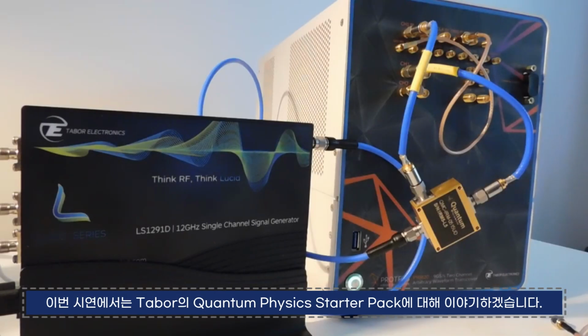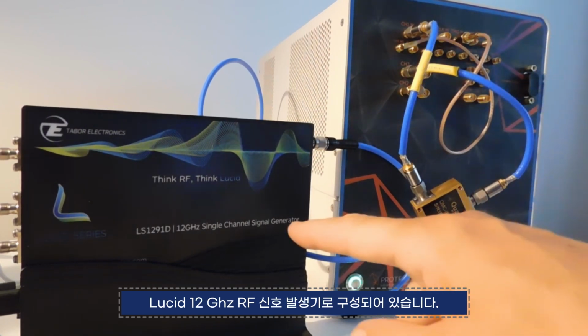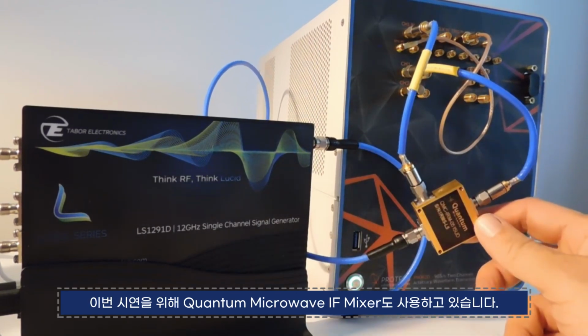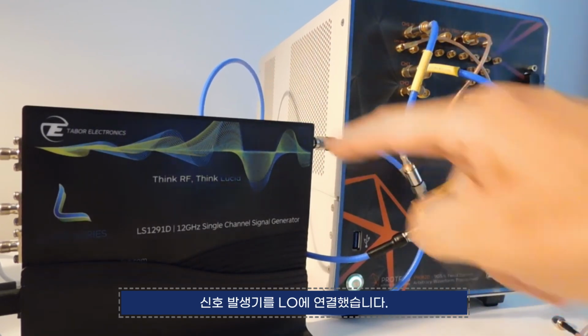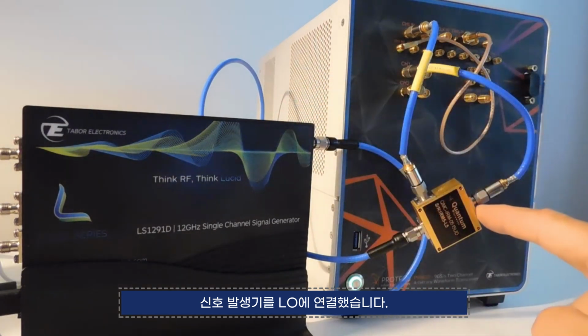In this demonstration, I'm going to talk about the Tabor Quantum Physics Starter Pack. It consists of the Proteus 1.25 gigasample arbitrary waveform generator and the Lucid 12 GHz RF signal generator. To make the demonstration work, I'm also using a quantum microwave IF mixer. So we've got the arbitrary waveform generator feeding the IF input, and we have the signal generator feeding the LO.